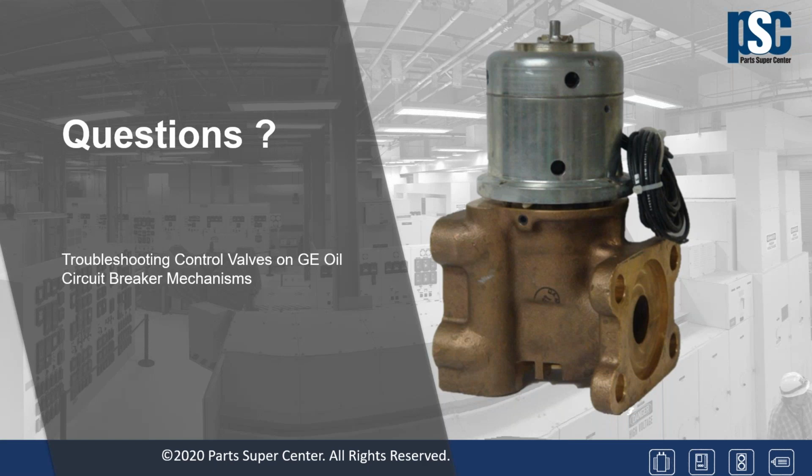So I would say that your most likely culprit is not the tail spring. Very rarely is it the tail spring, but that is really the way to change the opening tripping speed. But most of the time it's due to the grease on the trip latch roller within the mechanism. And we can get you the part numbers for the trip latch and the trip latch roller as well if you provide us with the serial number of your breaker. Additional questions?